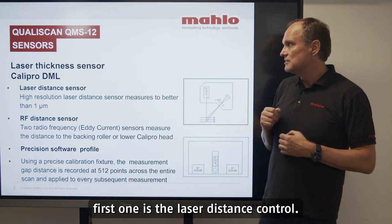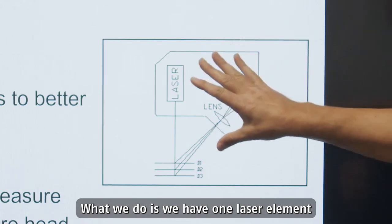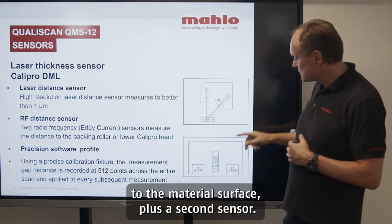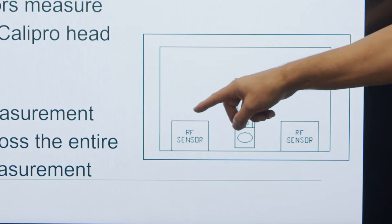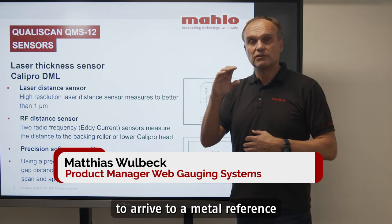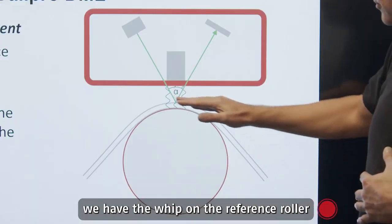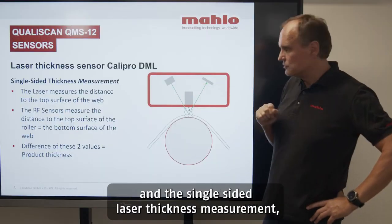First one is the laser distance control. What we do is we have one laser element that detects the distance from the sensor to the material surface, plus a second sensor, a so-called eddy current sensor, is detecting the distance to a metal reference underneath the product. If you look at this example, we have the web on a reference roller and a single-sided laser thickness measurement.